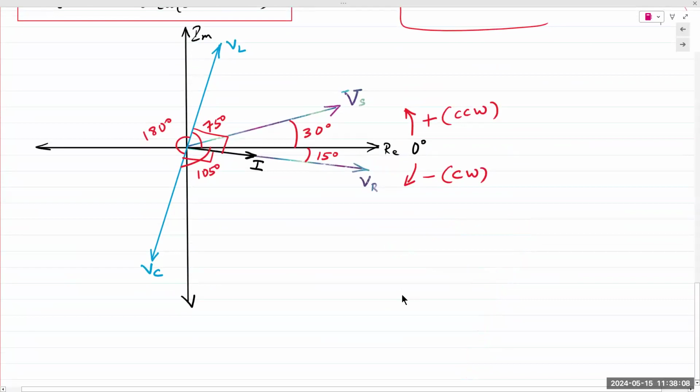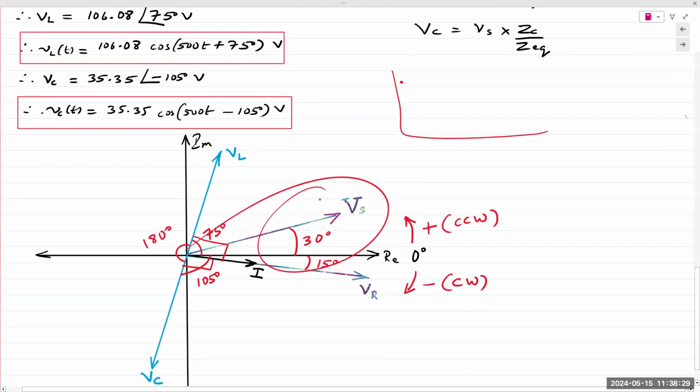Phasor diagrams, as I stated last class, all you need to plot a phasor diagram is the angle and the length, and these are plotted not to scale. You can simply take the angle, plot a line at the angle, and that's it. Mark and note it, and done. So voltage source Vs had an angle of plus 30. So you draw a line or an arrow at 30 degrees, note it as Vs, and that's it, done. You can note the magnitude, but I try to keep it clean. Otherwise, it was getting very cluttered in there.